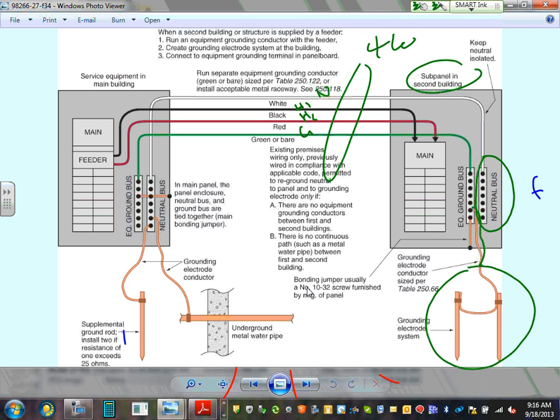At the sub panel, the neutral is not bonded again. You bond once. So you can see how the bonding happened here once, right? Do you see any bonding between the two here? There is no bonding whatsoever between the two. Right here, there's no bonding whatsoever between the two. Can you guys see that? Versus there is a bonding here. Maybe I should move it. Can you guys see that little main bonding jumper here? That's only done at the service. Only done at the service.